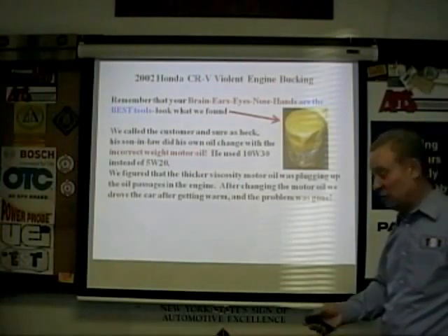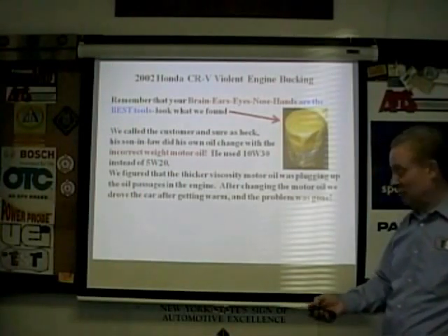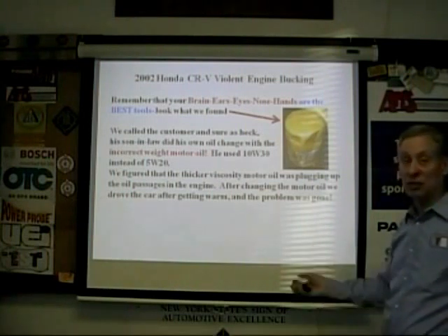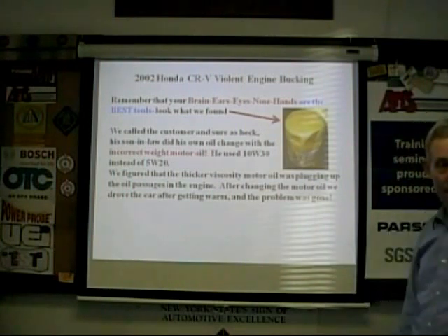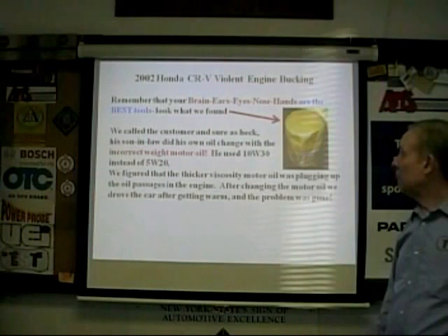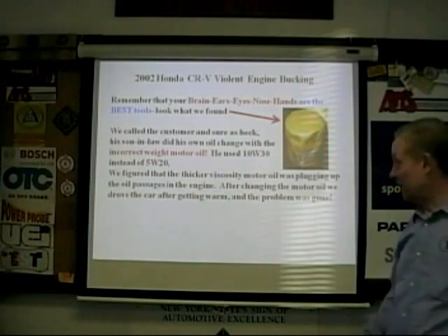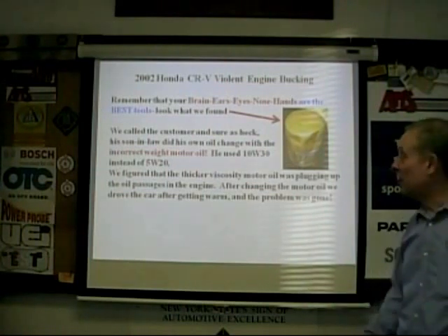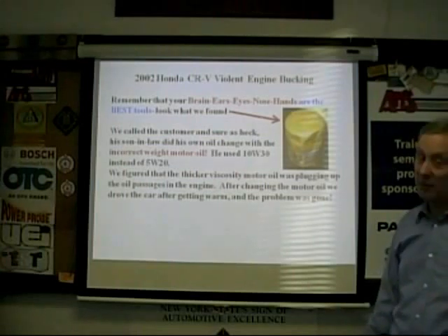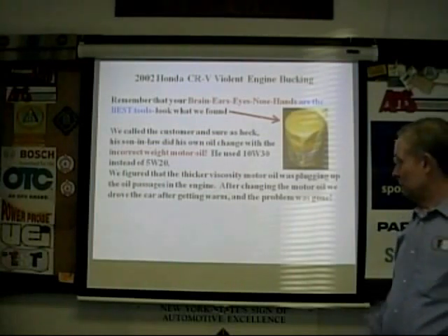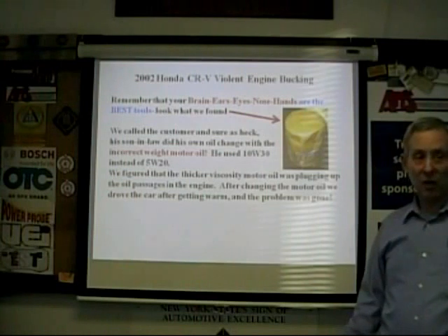If it's 10 below zero, we had some very cold days this winter, you might actually do engine damage. If it had happened in the summer, maybe it was hot enough that the oil thinned out and you wouldn't notice it. Or maybe you would. But in ALLDATA, they give you that information, what times of year and what temperatures you can use.